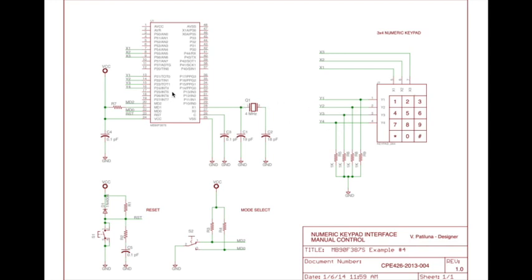because this is not TTL, this is CMOS. In CMOS, any input port that is hanging, the microcontroller would read that as 1, not 0. So to read that as 0 when there's no input, we have to pull it to ground.